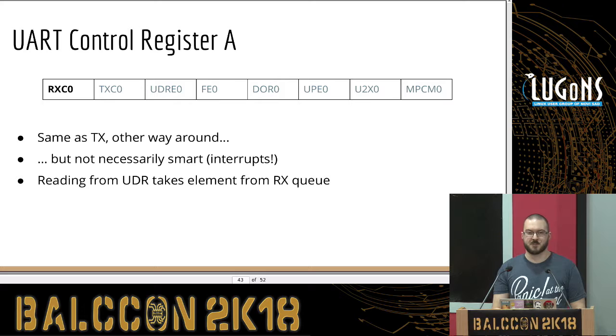Just busy waiting for the receive complete flag to be set would not be very smart. So you can put the UART controller to sleep and then wait for the interrupt to be triggered.